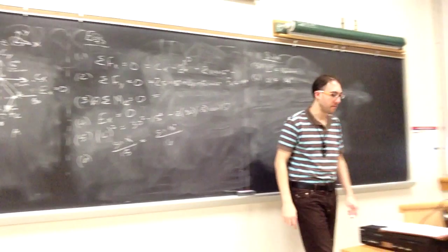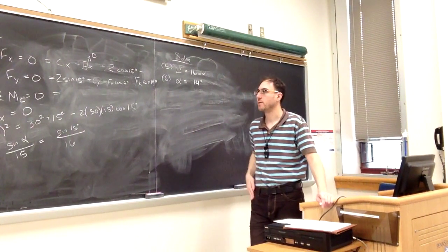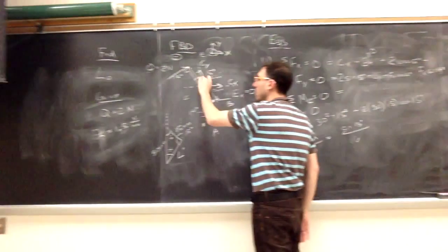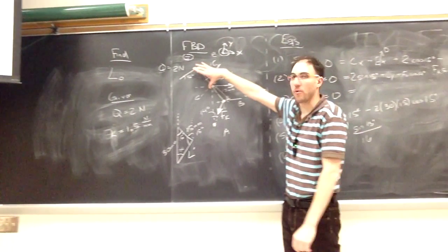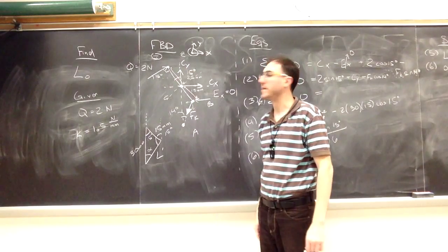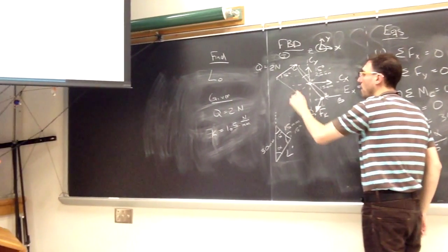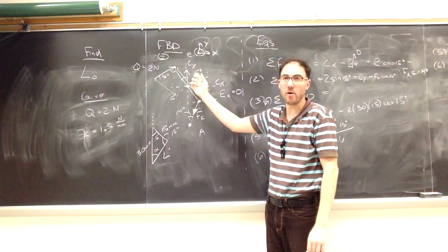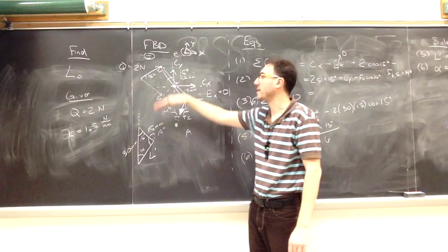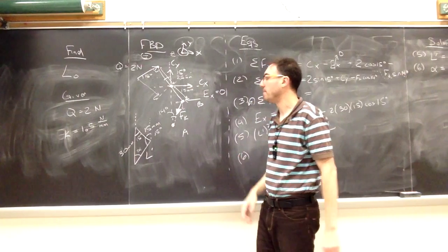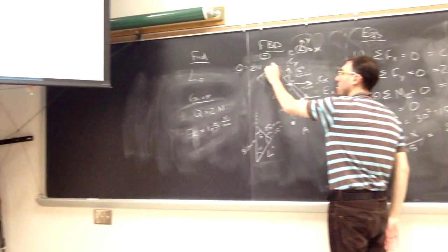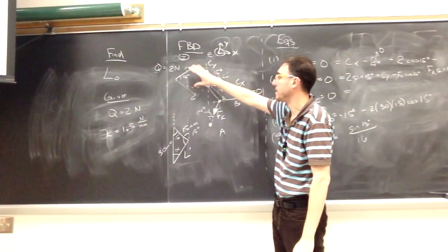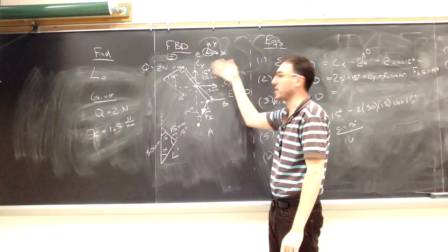What will the moment from the 2 Newton force be around C? This is a case, I'll say a relatively rare case, where we actually know what the perpendicular distance is of an oblique force. It's applied at 15 degrees, but because I know it's normal to the bar, I actually know what that distance is, the 25 millimeters. So in this case, I actually don't need to break it down into the horizontal and vertical. That would actually make it more difficult because the horizontal component, I can find it fairly easily, but I would need to find that distance, which would be 25 times cosine 15.